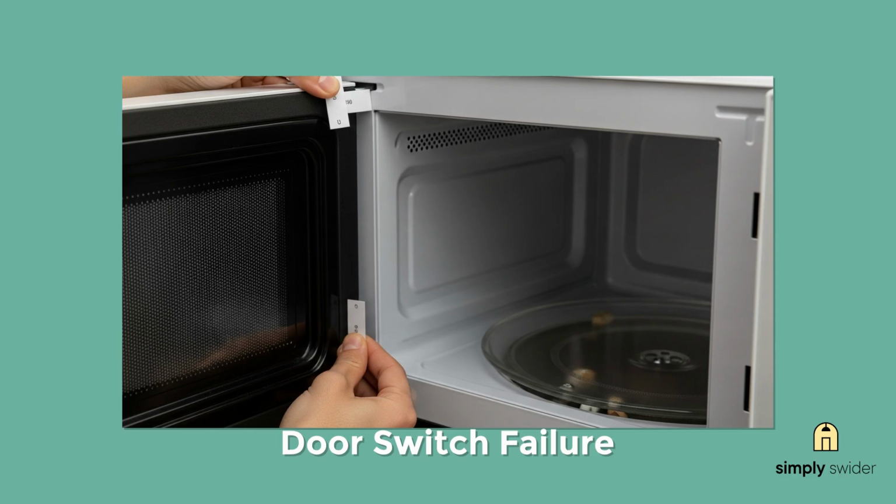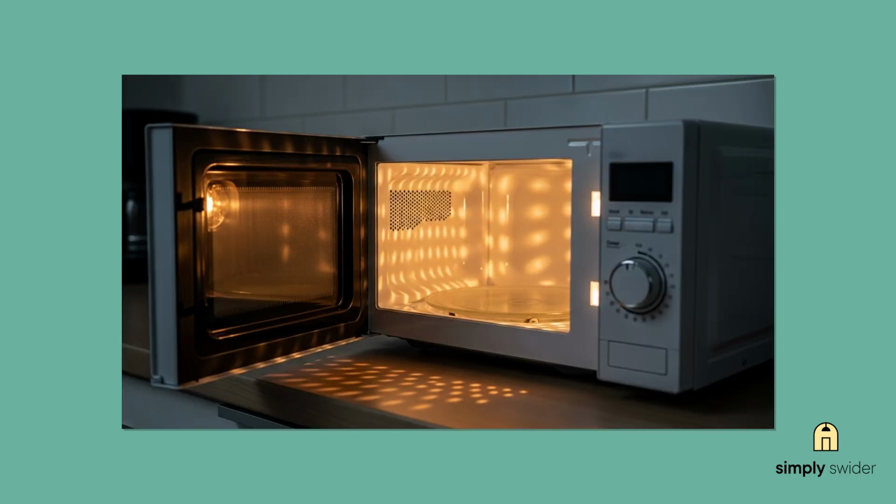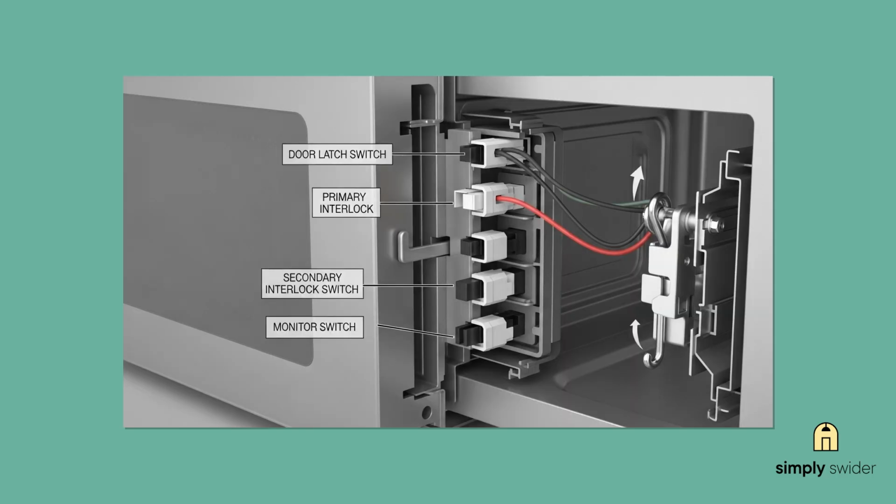You'll notice the microwave won't start, stops mid-cycle, or the light flickers when you open the door. There are usually 3 of these switches: primary, secondary, and monitor. If one's acting up, it can trigger the protective systems and cut power to the whole unit. Again, unplug first, then inspect the door switches for any obvious damage or misalignment.